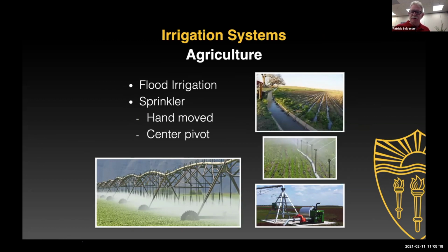Often these, not always, but often, this uses well water, which is fine because that doesn't deal with your potable drinking water system. If there's a tie-in from the well system to the potable water system, then you need to look at backflow protection at that point, because the well pump could actually create pressure higher than the distribution system pressure.